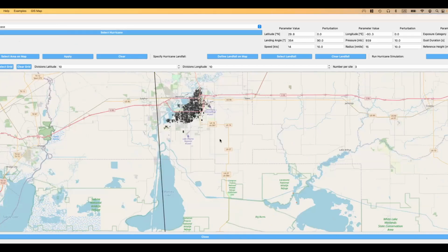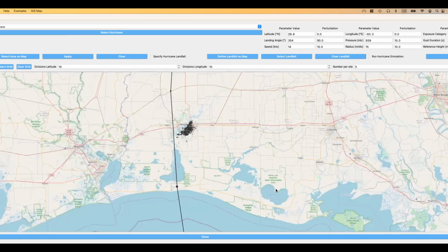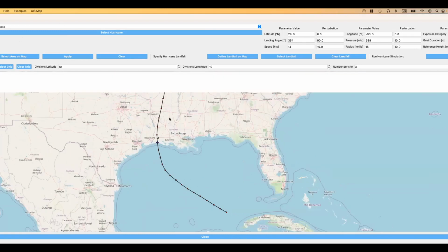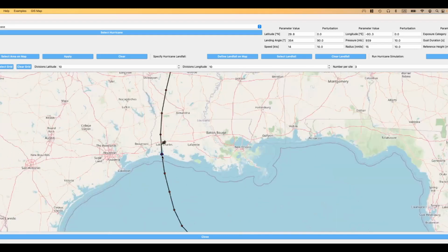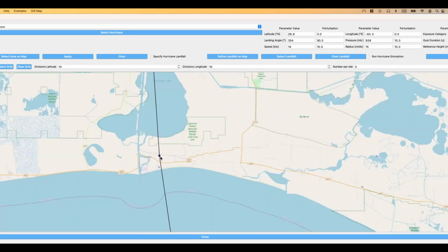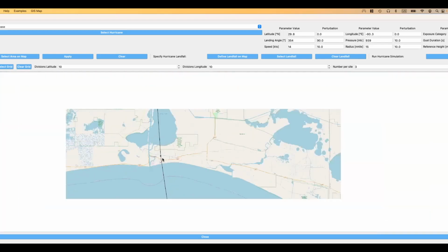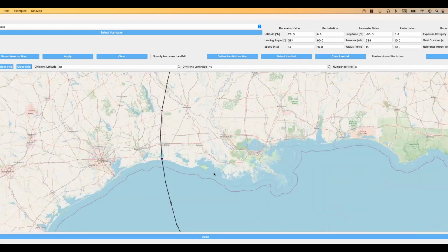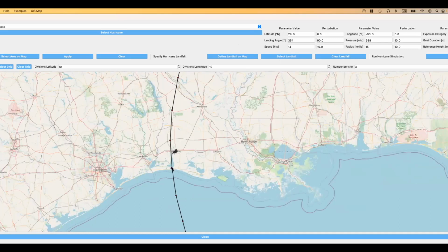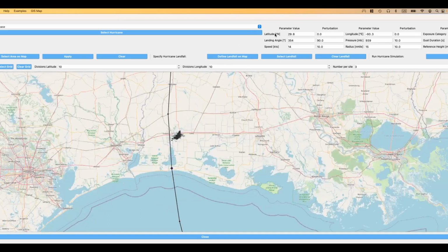I'm going to select this hurricane, and I'm going to zoom out, and you'll notice that this is the only one left there. And you'll notice each track point and this blue diamond here that specifies the landfall location. So using that database, R2D will figure out where the first landfall is. You'll have some hurricanes that make landfall twice, so you may want to change your landfall. You might want to clear it here and then define the landfall again somewhere. But in this case, I'll leave it the same. It's very simple. It'll pull the landfall values from the database that you need.